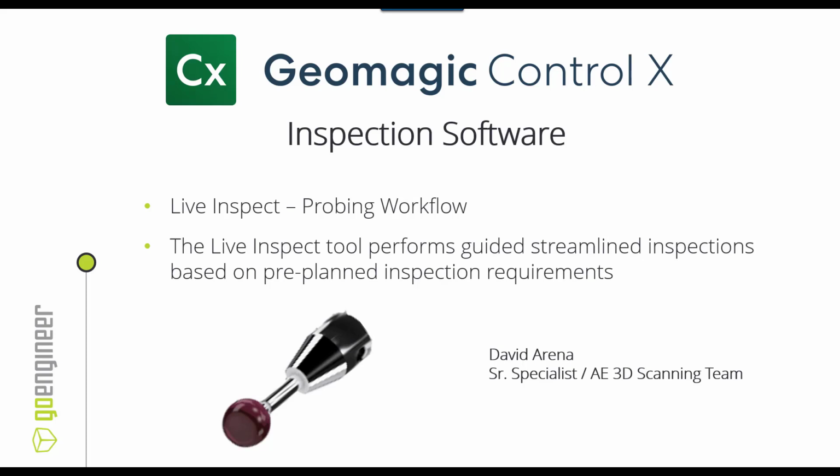Today's brief video is going to take a look at Live Inspect inside of Geomagic Control X inspection software. The Live Inspect tool performs guided streamlined inspections based on pre-planned inspection requirements. Basically what that means is we're going to start with a CAD model and we're going to put some dimensions on the CAD model that would reflect the inspection routine. From there, once we've established all the measurements that we need to take, we'll go ahead and launch the tool and perform the inspection. In today's video, we're going to focus on probing.